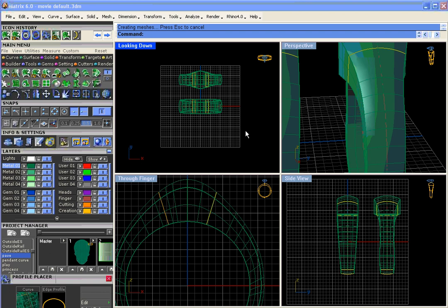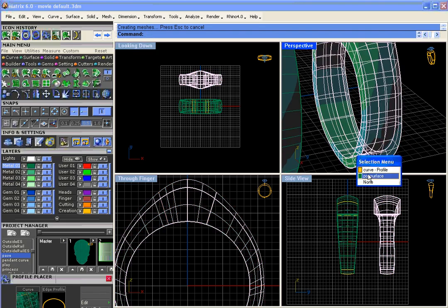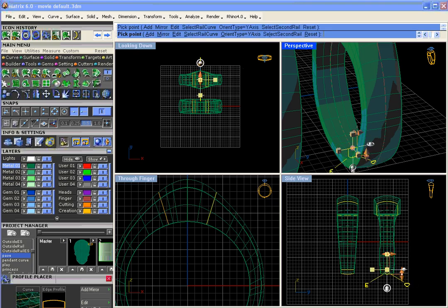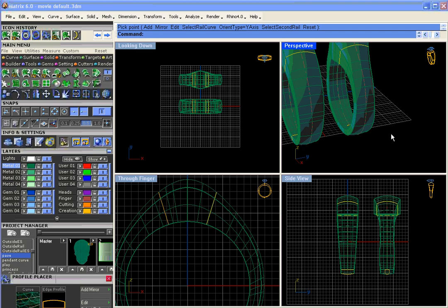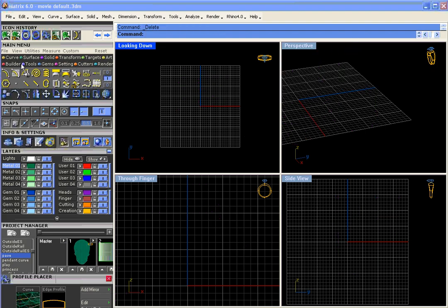You have the option to maintain height or to uncheck maintain height in the dialog box when doing your regular Sweep 2. The difference is if I come in here and make some changes, change the width, it doesn't care because there's no history involved with this sweep. It's the traditional regular Sweep 2 without history. So the traditional Rhino Sweep 2. Another thing that can be done, a nice feature with the old Sweep 2.